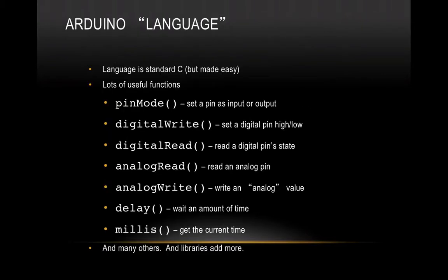The Arduino language, as we said, is pretty much similar to C, C++, but much easier than C, C++. So there are a lot of functions which are used to control the hardware. Some of the functions are like pinMode, which sets a particular pin of the microcontroller in the Arduino hardware to being an input or an output. Then, if we want to write a high or a low value to a particular pin, then we can use the